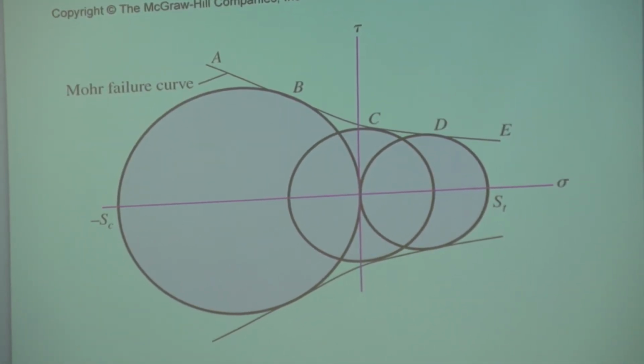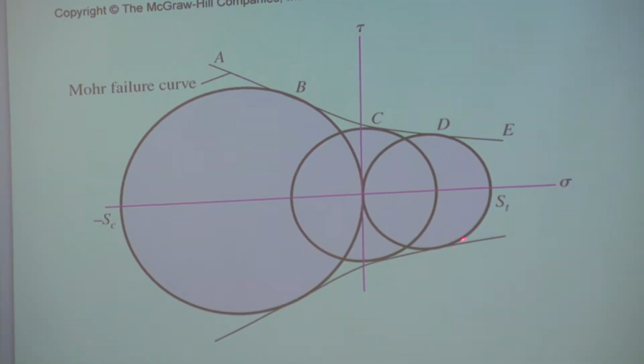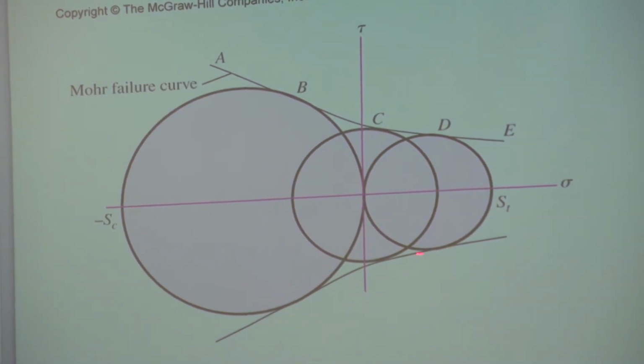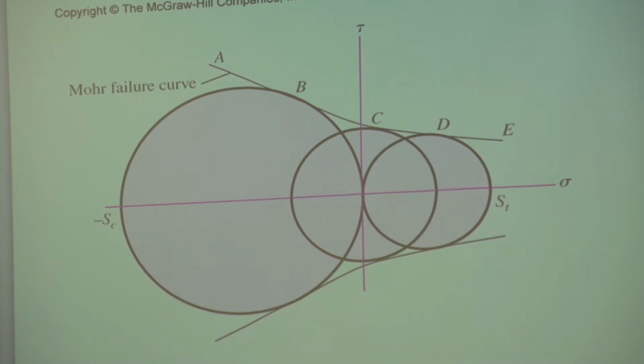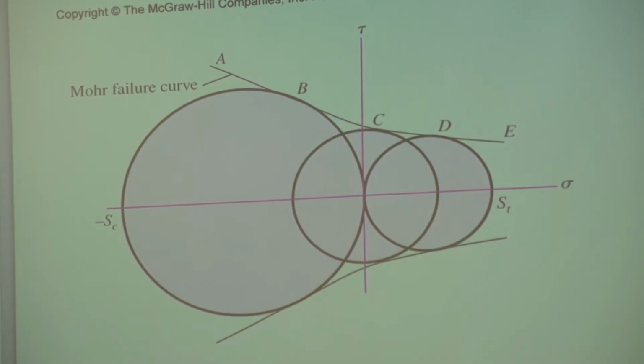It is based on three tests. This is the Mohr circle for the test of a brittle material in tension. And this is drawn exactly as the material is about to fail. That's equal to the tensile strength. Does everybody follow that Mohr circle? A single, one-dimensional stress. You only have one normal stress, no shear stress. So your Mohr circle, maybe I'll draw it over here.